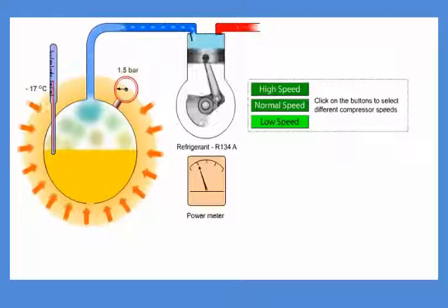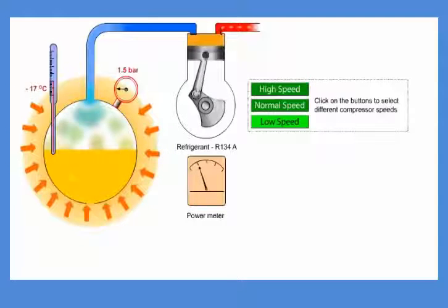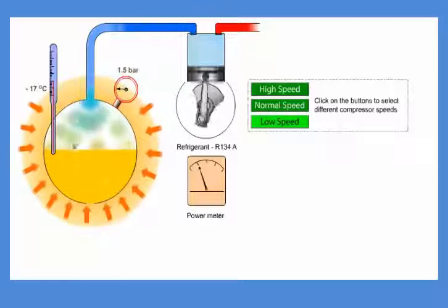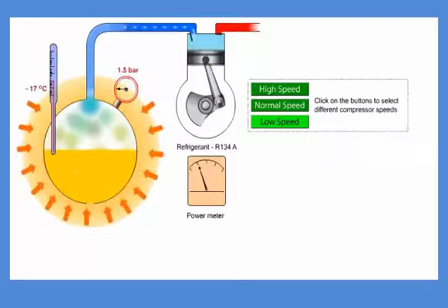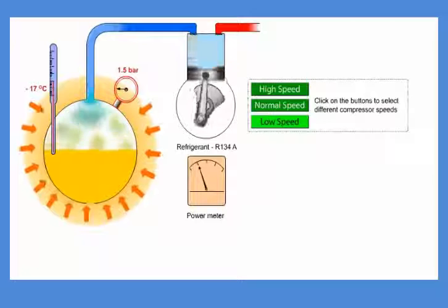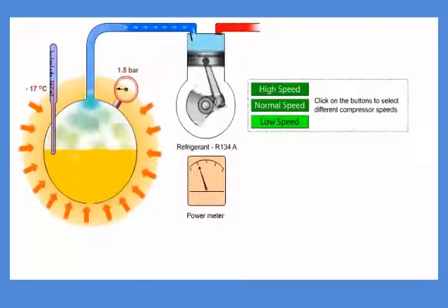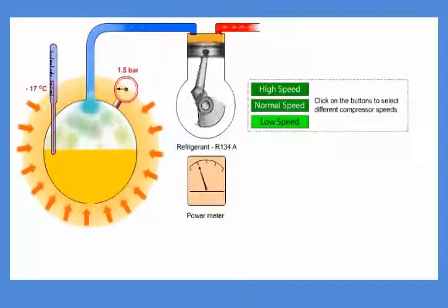This will again cause a reduction in evaporation, as you can see, which will stay on this level because the temperature difference between ambient temperature and the evaporation temperature in the flask is now lower, giving a decreased heat transmission to the flask. Again, a new equilibrium is established.